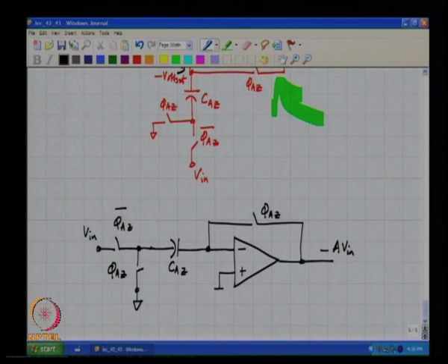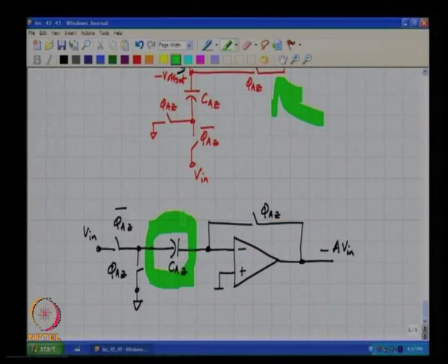All right. So notice that this capacitor CAZ is basically acting like a battery which holds the offset. We also need to subtract references. So what do you suggest we could do? Please note that CAZ is simply acting like a battery which stores the offset.